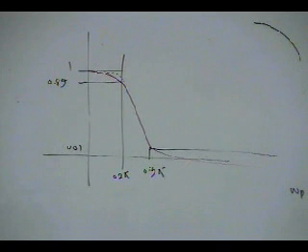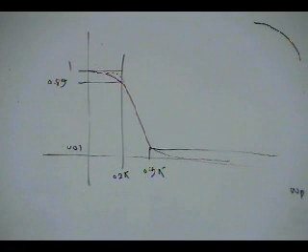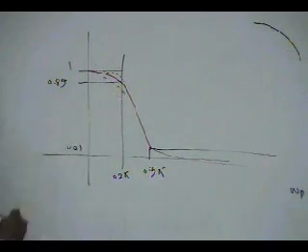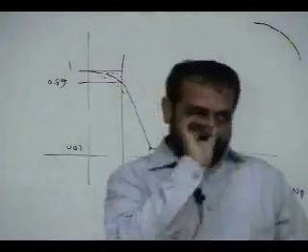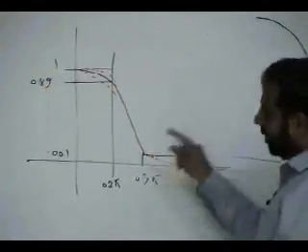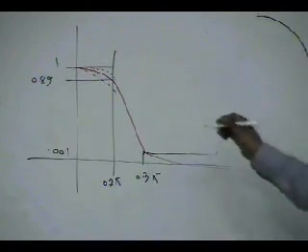It is an over design. It will be a higher order filter, flatter. Anything which is flatter than this means capital N will be bigger. Anything which goes below this is under design, it is not meeting specs. So a filter which meets specs is guaranteed to pass through this point and this point.